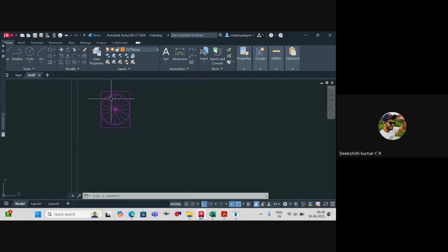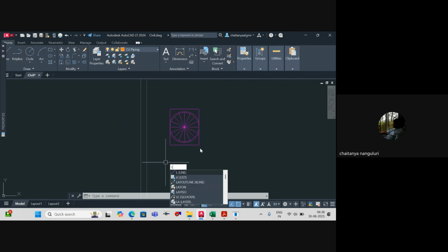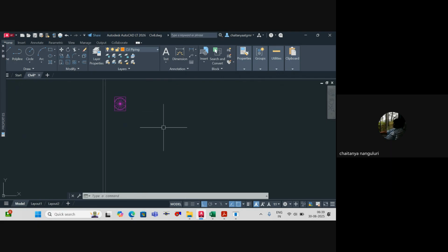First, I'll create something called a refnet joint. What is a refnet joint? You remember it? One pipe is connected to two separate pipes. That is one refnet joint. If you have more than that, you call it a header set, but we don't use it; we generally use the refnet joint. So I'll create a small refnet joint, something like this, and I'll take it as 1 inch.